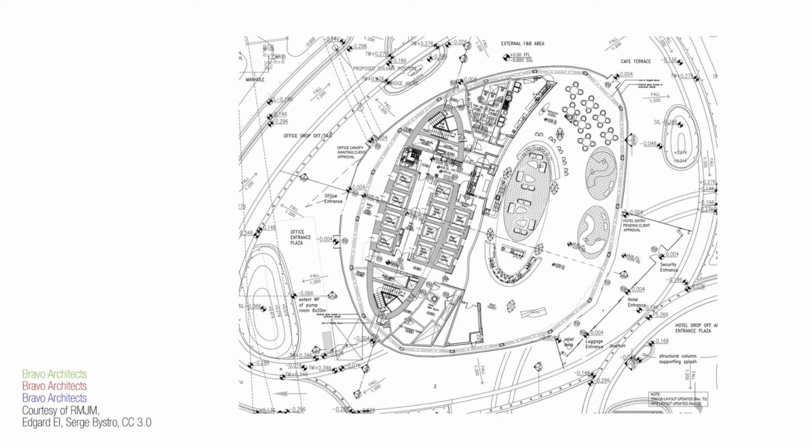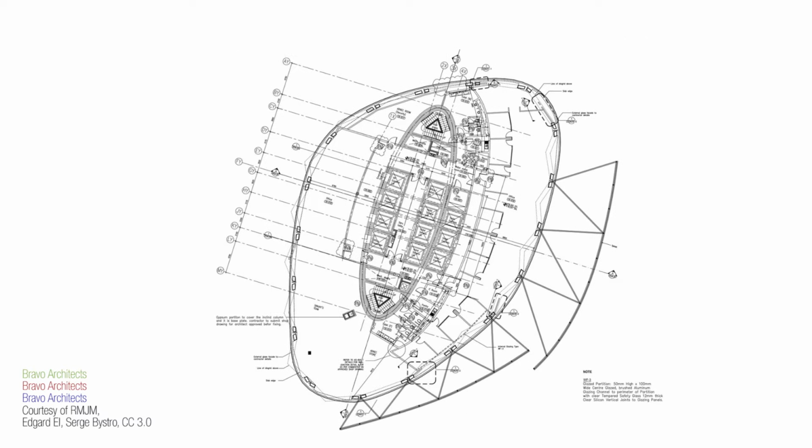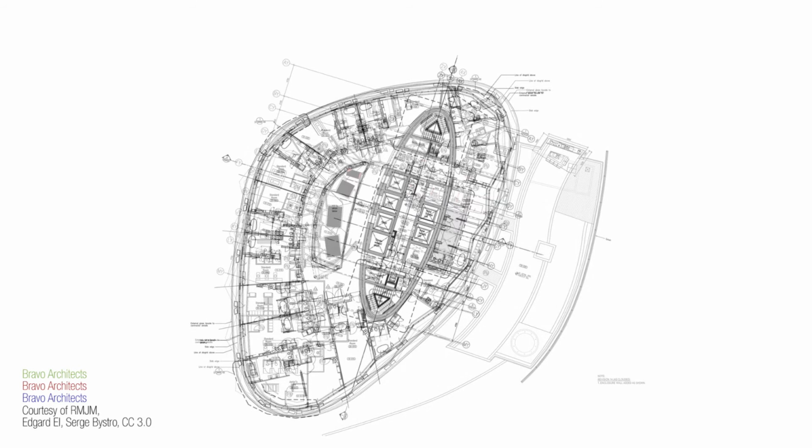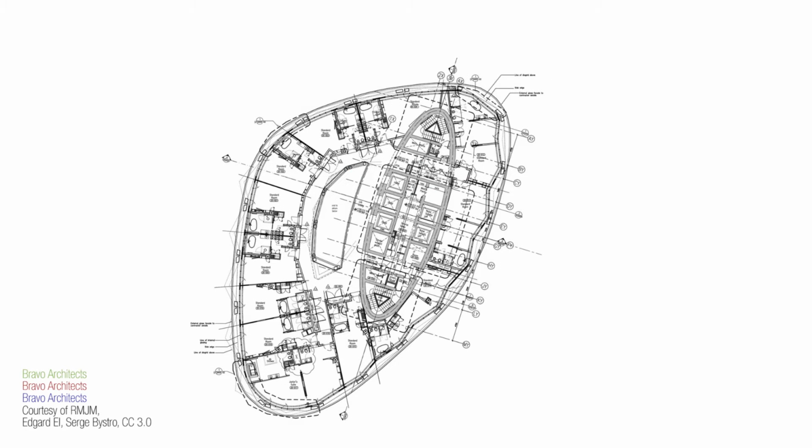On the ground level, the floor is attached to the core on the right side. However, on the 16th level plan, the floor area on each side of the core are more or less equal. And this is the projection of the ground floor plan on this level. On the 19th level plan, 3 outer elevators are overrun because the space on the right side is getting narrower. And on the 20th level plan, there are already different functions instead of those elevators.